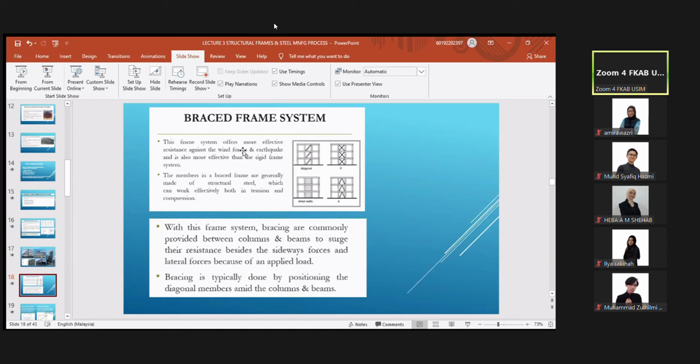So if the building goes up the same size, like our 118 tower, then the lateral load is very, very strong, and it may affect the foundation. Maybe our building foundation is not big in terms of scale. Talking about just like a finger pointing up, it is thin, very high in terms of scale. Maybe the wind force is being reflected through the curved edges of the 118 tower. If you have a block of square rectangular shape that goes up like 80 storeys, you have a problem of lateral load. Lateral load comes from the side; the wind can push the building.